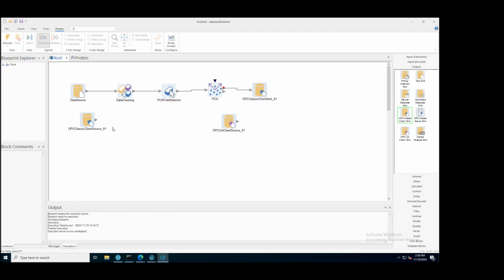So please bear in mind that all you see here is a tool for the process engineer to do the analytics on the data. The end result could simply be, as Cameron indicates, a simple indicator on an HMI SCADA screen saying, hey, the blade needs to be changed or not, or a percentage of how worn it is. So all this runs eventually in the background.